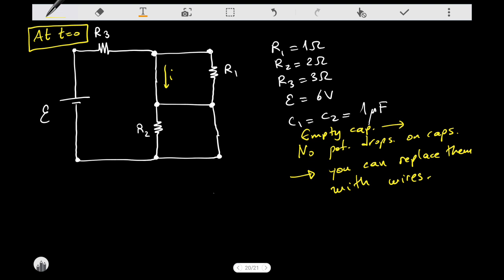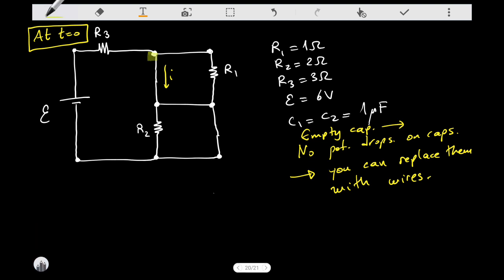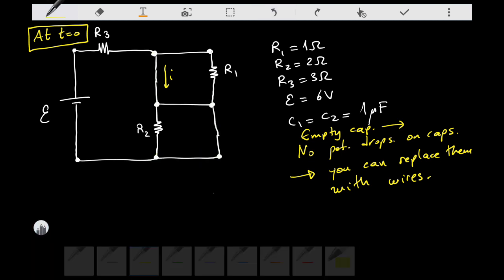What I notice is that this part of the connection from this point to that point is just connected by wires with zero resistance, which are connected with resistors with finite resistance. But you can see that the equivalent resistance between this point in here and that point is equal to 0. So it is quite easy to see that the current follows over the path that I have just traced out.